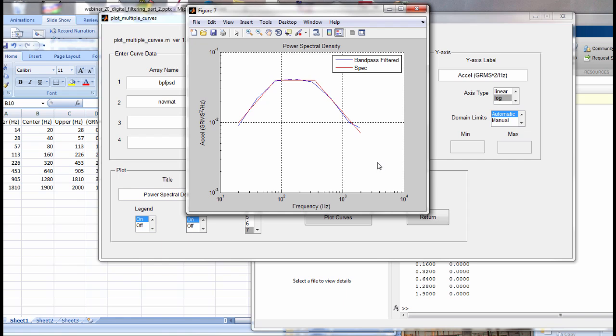So anyways, what we've done is we've shown how we can use a successive bandpass filtering method to calculate a power spectral density. And again, please do this as an exercise. Now, imagine back in the olden days, even before I was born, and someone was trying to calculate a power spectral density using just analog equipment. Well, they might have had the random data, for example, on a magnetic tape, so they might have played that through an analog bandpass filter and then an analog overall RMS meter.